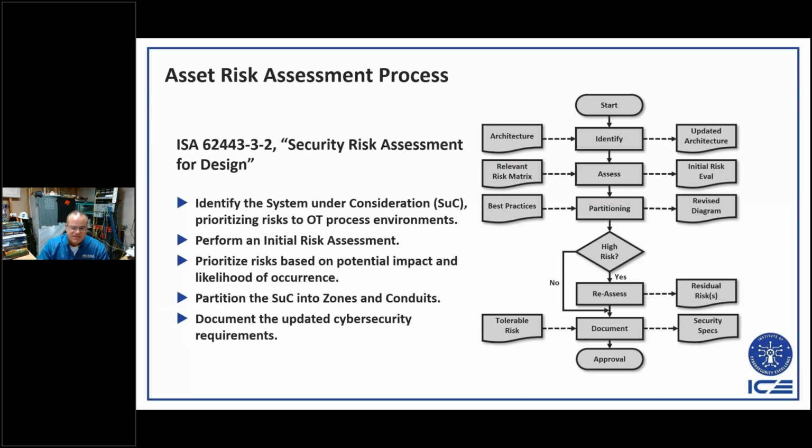identifying the system under consideration, prioritizing the risks to the OT process environment, performing that initial risk assessment based on potential impact, partitioning those zones and conduits as Sinclair had described in the balance of the presentation he gave ahead of this one, and then documenting and updating those cybersecurity requirements.